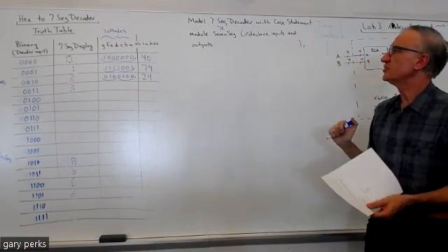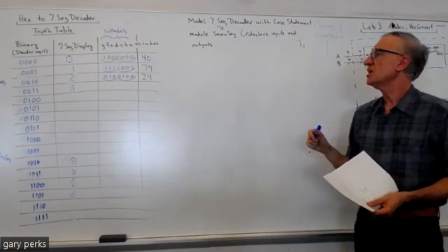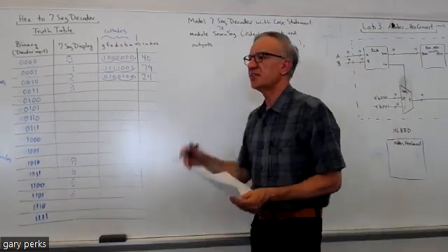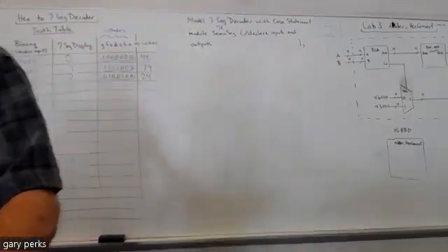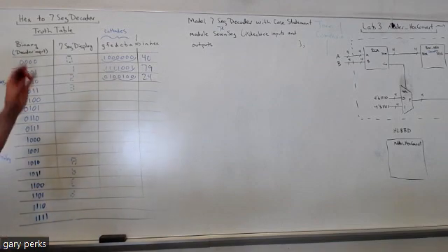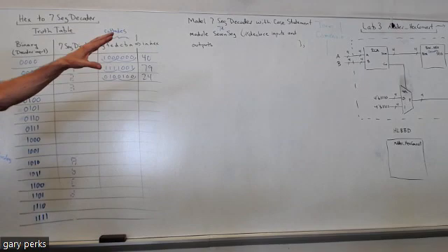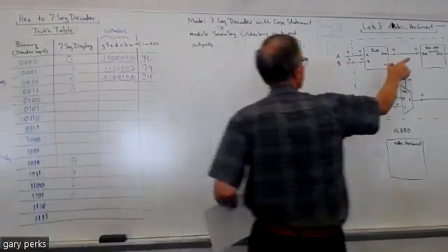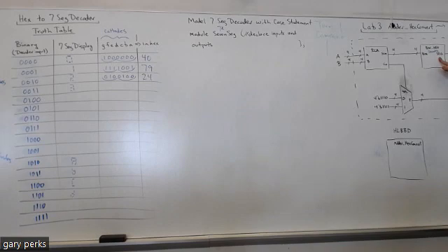Okay, then you would declare your inputs and outputs, just like before. You're gonna see that just like when you did the if statement for the MUX last week, for this decoder, we're gonna use a case statement. And when you use a case statement, it also has to go within an always comb block. And last time, you know how we talked about that any output within an always comb, you got to write output logic when you declare it. Well, same thing here. So see, we're going to have this output seg that's going to be within an always comb. You're going to see that coming up.